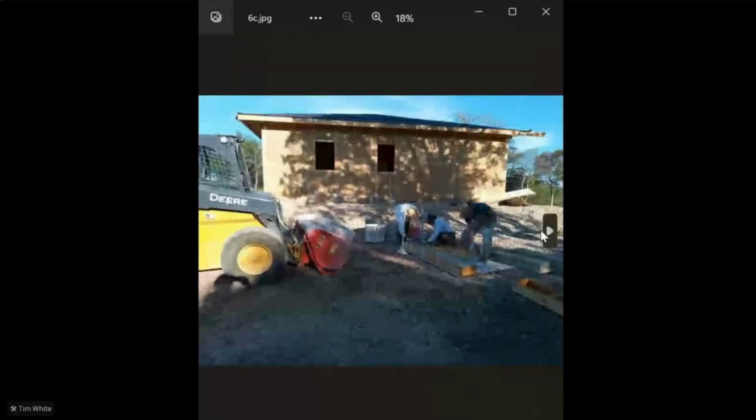At the very top here, you can see we brought hempcrete up here to the top, but we haven't filled it up to the top of the rafter. And so what we decided to do at that top 12 inches, 16 inches is we went outside and made some blocks that were the same size to slide up in between that 2 foot on center engineered hip truss system. And then we just masonried those blocks into that space. And so we avoided having to beat your head up all the time trying to get that hempcrete up and over that little top spot that you just have a couple of inches to get into.